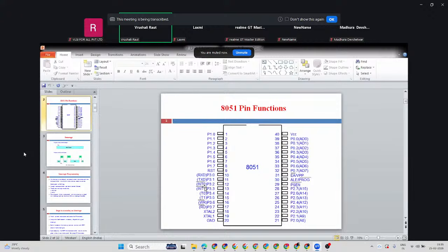So what are the two interrupts I'm checking for my washing machine? One is about the door and the other one is about the water tap. Is it flowing or not? Water is there or not? Both the things are very important. So what will happen in the starting? I am putting the cloth in the washing machine, putting the detergent in the tray, and then I set the program and I start the button. But now what is happening? The program will not start running. Why? Because at first it will check the interrupt. Which interrupt? Door interrupt. And as the door is not closed, an error will come out there, right?